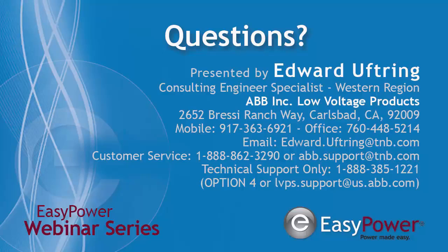Current limiting, I'm running out of time. So current limiting really is achieved by using the magnetic field that's induced by the high current. We then pop immediately on our movable contact. Basically, we get the rating by going through UL and passing their test.